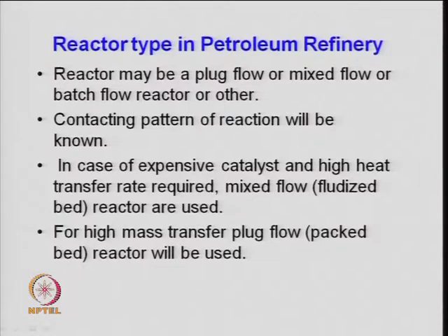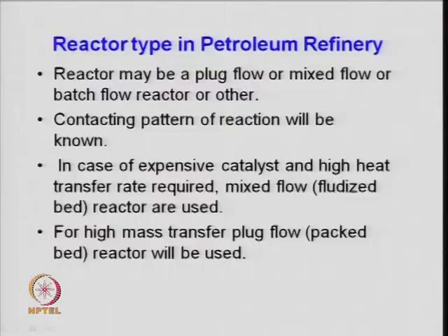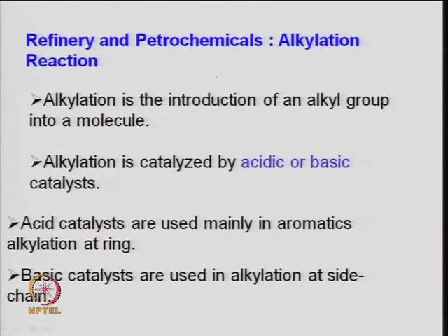And suppose the catalyst is very expensive. Then heat transfer or removal of heat is important, otherwise the catalyst life will be damaged. So, you prefer a fluidized bed reactor because it is easy to dissipate heat. Then mass transfer is again an issue. For high mass transfer you prefer a plug flow reactor, with high velocity at high superficial velocity. All these kinds of reactors are used in refinery and petrochemical reactions.